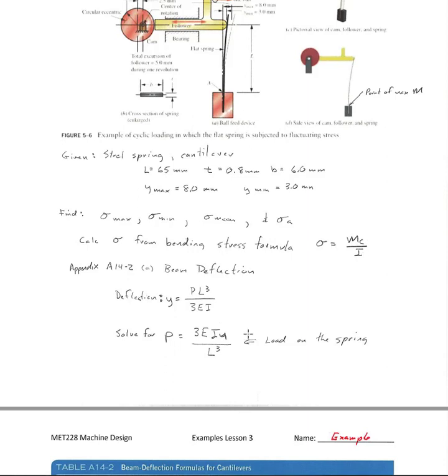So we're going to be calculating our stress from the bending stress formula, sigma equals Mc over I. And to do that, we have a relationship between load and deflection that we can actually get from Appendix A14.